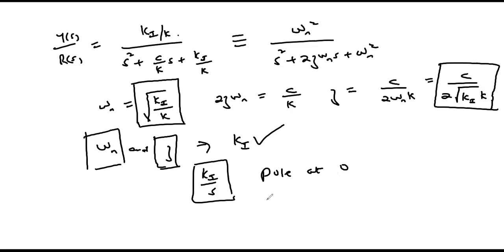And therefore, the second shortcoming of the integral control action is the effect it has on the stability of the system. It affects the stability of the system negatively, pulling the stability of the system to the point of marginal stability. And in some cases, depending on the nature of the system, it may actually become unstable.